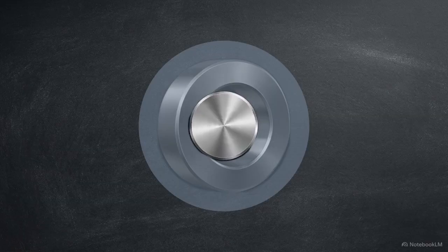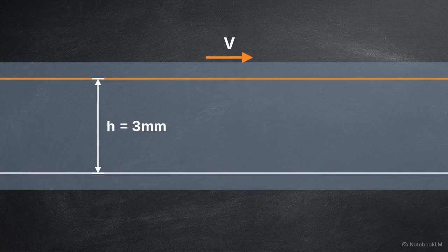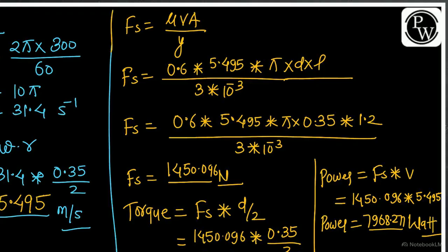Now we map the circular geometry onto our linear model. If the shaft surface is unrolled, it acts just like our moving top plate, traveling at our calculated linear velocity over the 3mm fluid gap. Plugging our converted viscosity, velocity, surface area, and gap thickness into the linear formula yields the final result. The oil exerts a constant shear drag of exactly 1,450 newtons against the rotation of the shaft.